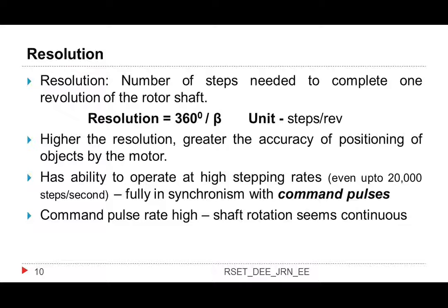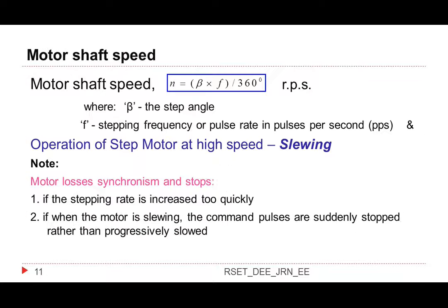Now, the stepper motor has the ability to operate at high stepping rates, even up to 20,000 steps per second, fully in synchronism with the command pulses. That's an important aspect. If the command pulse rate is high, the shaft rotation seems to be continuous.